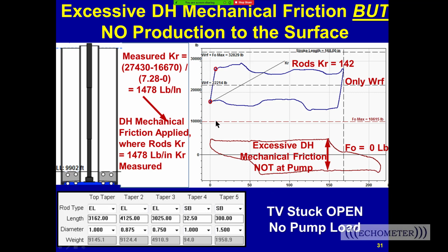Just to stay on the same point, we have Walter who's on this point asking if you can clarify the PRT setting the pump card at 0 loads. Is that how it determines surface load offset? Right. On a horseshoe load cell, the horseshoe load cell is like a bathroom scale, and before you step on it, you adjust it so that it reads 0. That's what a horseshoe load cell does.